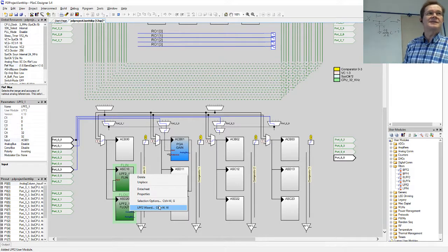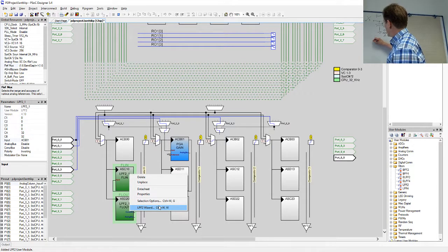A simple device that can be easily integrated, since resistors are hard to integrate on any integrated circuit. Capacitors are easy. Switches are easy, those are just MOSFETs. And that way you actually have a variable resistor, where you vary this one with the clock rate.